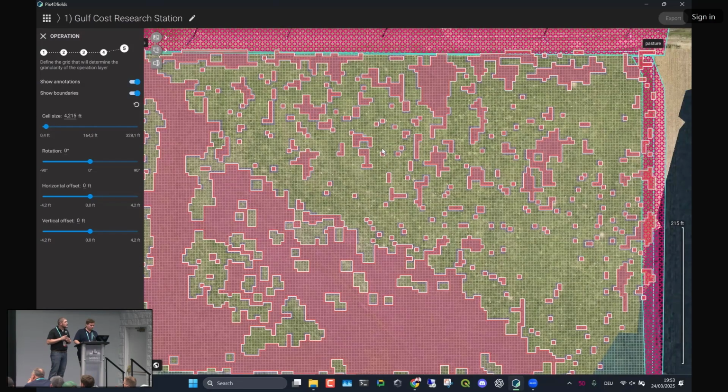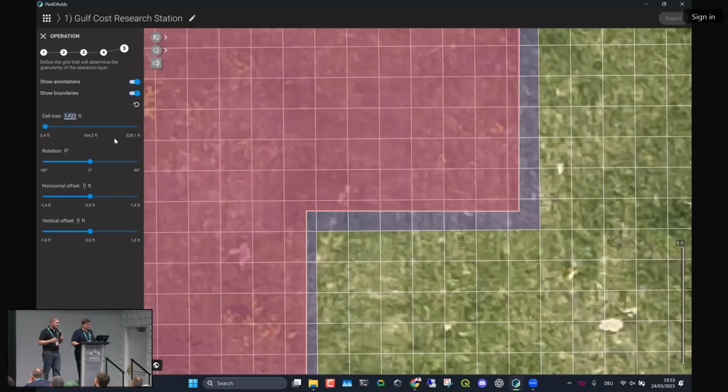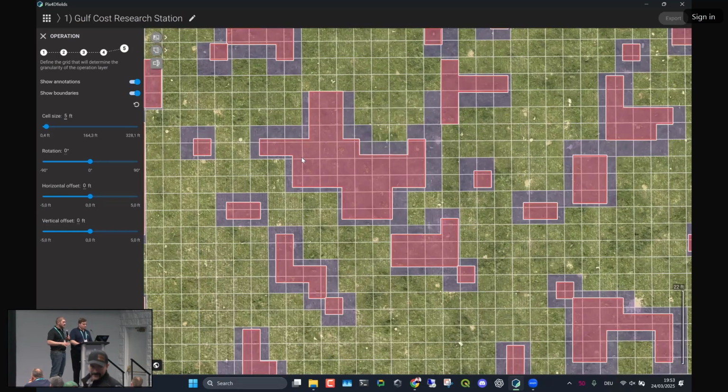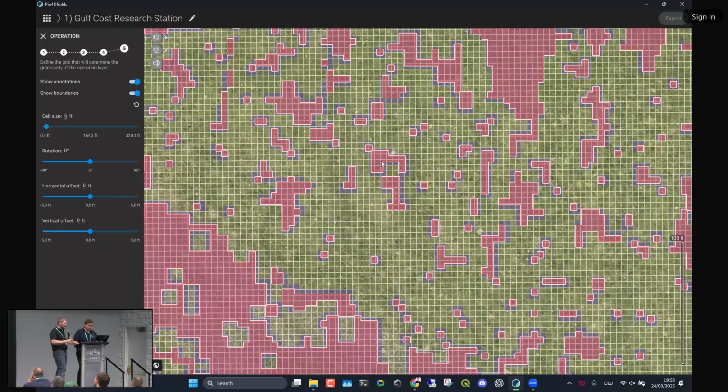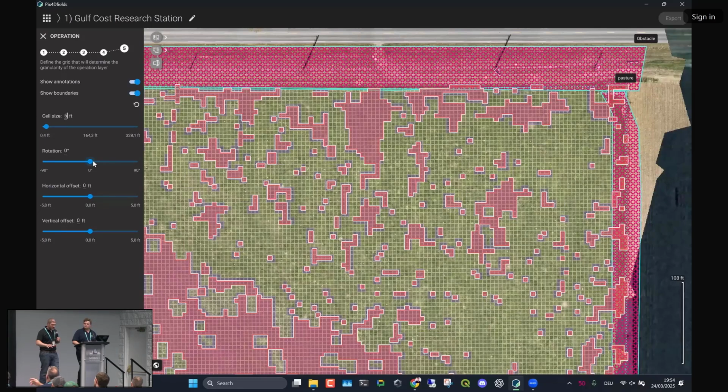Is that accurate enough to work on a PWM nozzle sprayer that's running 20-inch sections? Yes. I mean, again, this comes into geolocation and making sure everything's right, but yes. It also depends on how the company that we import to deals with the data after, because some of them will sample that data and pull it in differently, and some of them will use what you give them. It's a little bit different depending on what monitor you're using, like John Deere, because sometimes they downsample something. So you might have a block here and it'll spray a huge area. So it's kind of mix and match.